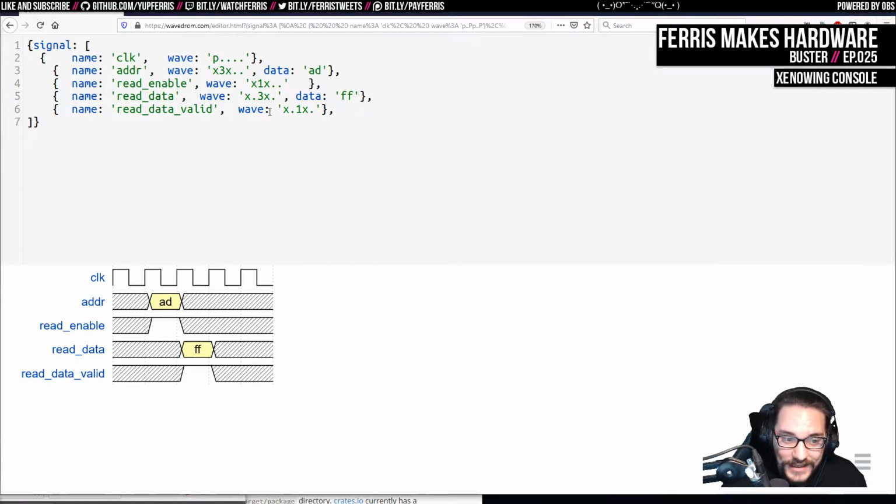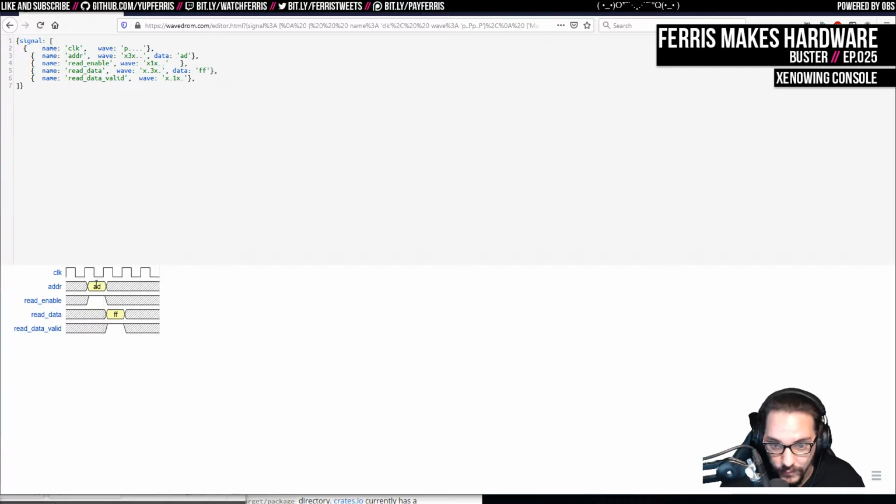Now this is called a synchronous memory, and so before what I had, the read data is only valid on the cycle following. After that cycle, the data is essentially lost. This could have anything on it. The old ones were like this, where as soon as you issued this, on the same cycle, the data would come back. The main consequence here is that everything that needs to read from this needs to latch the new data on the following cycle. It needs to be aware that it needs to do that, and we need to account for that 1 cycle delay whenever we use these. So we have to design a bit carefully, but it's not too bad.